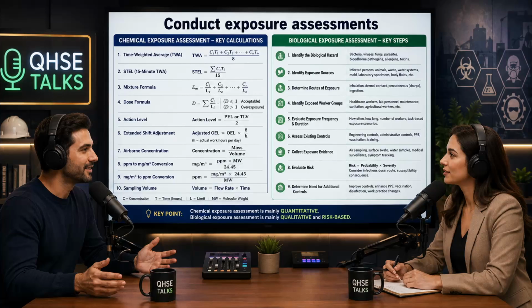The IDLH was originally developed by NIOSH specifically for respirator selection. It defines an atmospheric concentration of a toxic, corrosive, or asphyxiant substance that poses an immediate threat to life, or would cause irreversible or delayed adverse health effects, or, and this is key, would interfere with an individual's ability to escape from a dangerous atmosphere. Meaning, if a chemical acts as a narcotic and makes you dizzy and confused within 2 minutes, you literally can't find the door to escape.